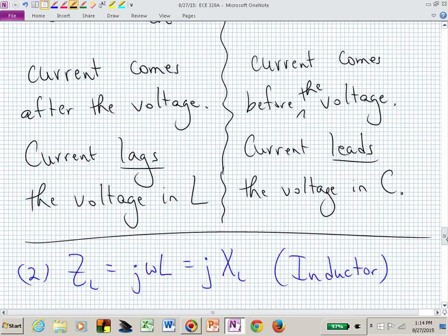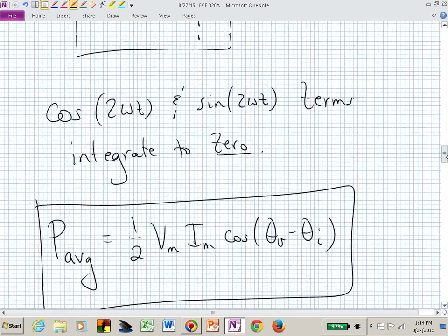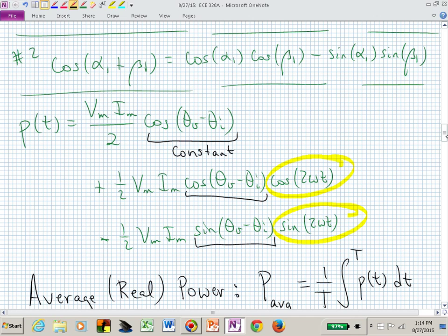Well, if we go back to that early derived instantaneous power formula, what can we see from that? The first term vanishes, doesn't it? What about the second term, or the middle term? It's gone also. What about the third term? Sine of 90 is 1, isn't it? Now we have the instantaneous power of an inductor going up and down, up and down, twice as fast in frequency as the voltage or current by themselves.